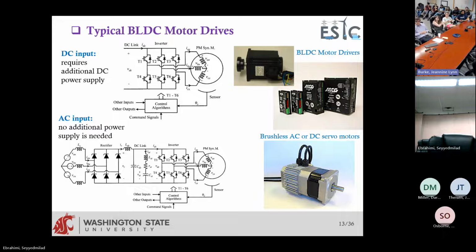If it was an induction machine, did you expect it to move? Of course, yes. But what if it's a synchronous machine? Something else needs to spin it first, and then it'll synchronize, and then it'll run on the wall power. That's exactly the reason. You have an MMF of a stator that is connected to the outlet, so it rotates with a speed that corresponds to 60 hertz. But the MMF of the rotor of the synchronous machine does not move. It's still stationary. You need some mechanism to spin this up so that the output voltage generated by the machine also matches the 60 hertz, then you can synchronize.